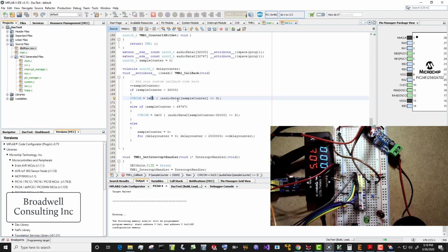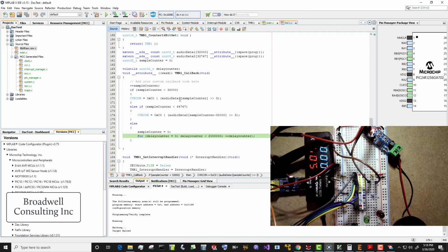16,000 interrupts per second is a bit much. One of the things that we could look at here, maybe you can hear that running in the background. One of the things we could look at here, this chip has DMA. The DMA is not capable of directly accessing the flash memory, only the RAM. However, it is possible for us to map some of the flash memory into RAM space in the extended data space and then access that with the DMA. However, that seems like an awful lot of trouble.